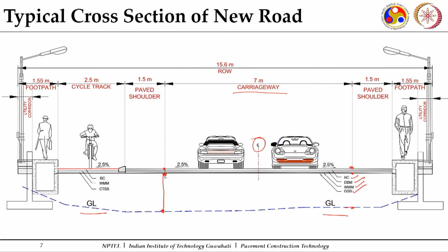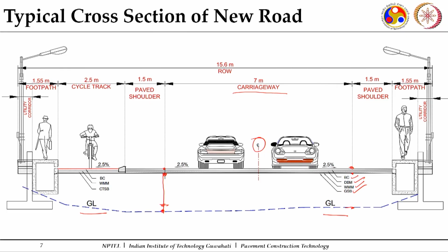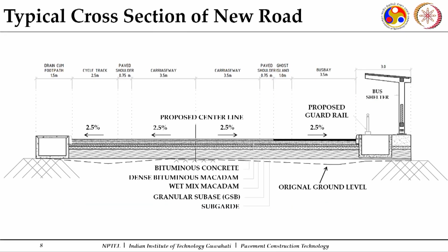So, I'll do the construction layer-wise, and with this center line, I'll fix the levels for the top of the first layer of embankment. Similarly, I will work out the levels at the bottom of my subgrade. So, with this I can figure out the levels which need to be achieved during construction. A good surveyor team will help you carry out this exercise.